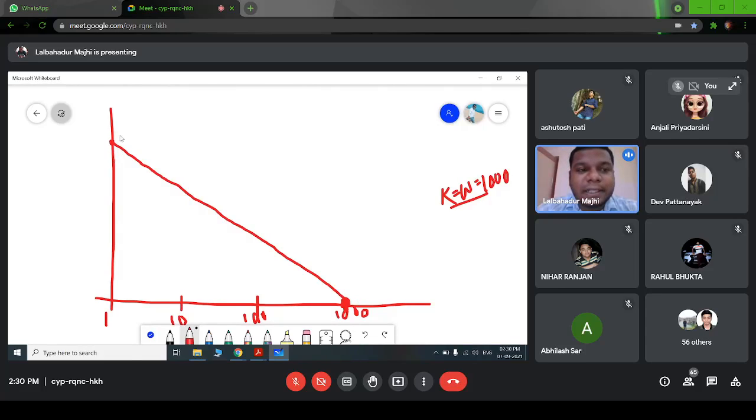We cannot find the starting point from the y-axis for a type 1 or higher system. Only for a type 0 system can we find the starting point by doing 20 log k. For a type 1 system we have to identify the point where omega equals k, which is 1000. So from this point we have to draw this minus 20 dB per decade slope.